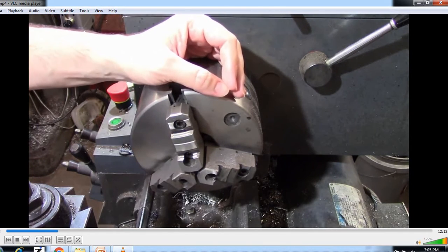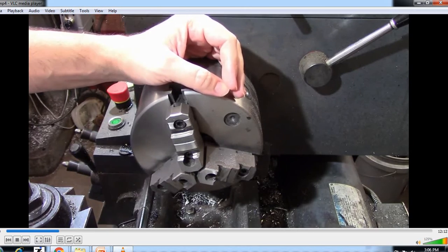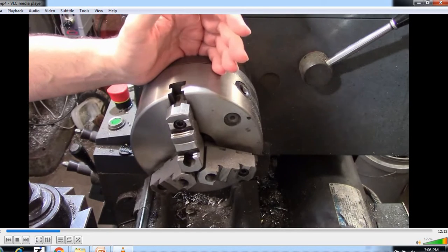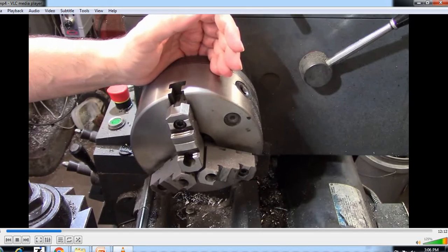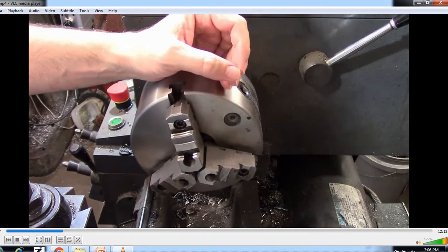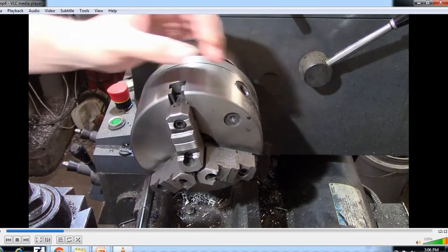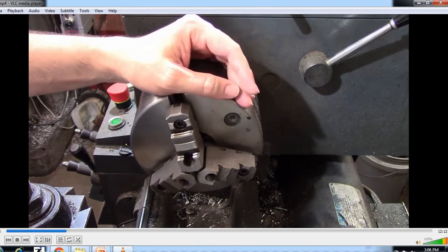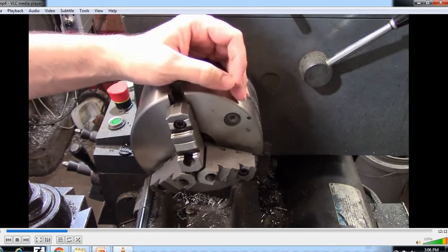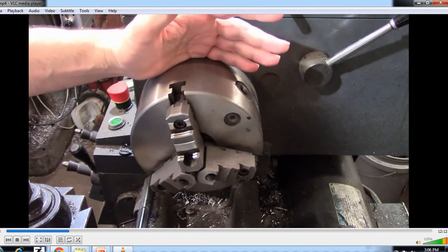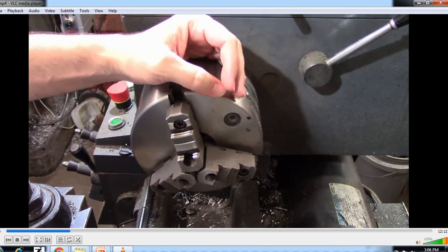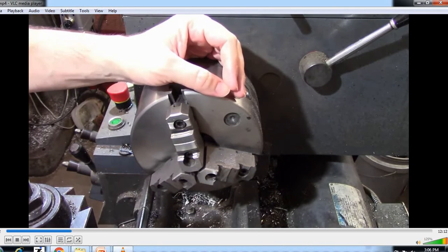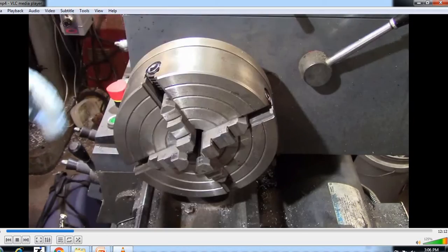It's not uncommon for cheaper chucks and old worn-out chucks to have a lot more runout than just 3 thousandths. As long as you know this limitation, though, you can work around it, doing all of your machining in one setup. If your part has loose concentricity tolerances, or none at all, then universal chucks are generally the fastest method of work holding for the lathe. Universal chucks are available in 2, 3, 4, or 6 jaws, with 3 and 6 being the most common.